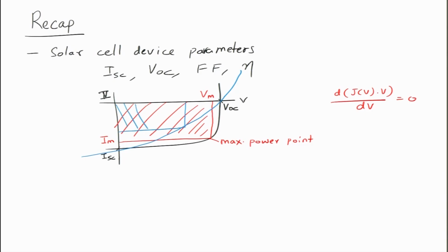Okay. So, for a bad solar cell, the fill factor is lower than that of a good solar cell, right. You can see that the area of this red rectangle is bigger than the area of the smaller rectangle, and this is for approximately the same VOC and ISC, and this is manifested in fill factor.